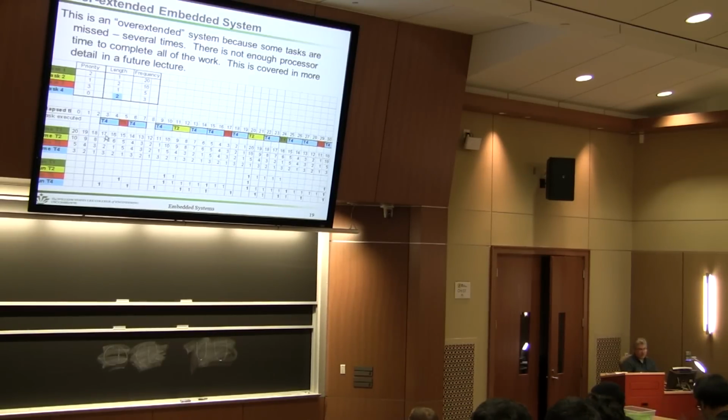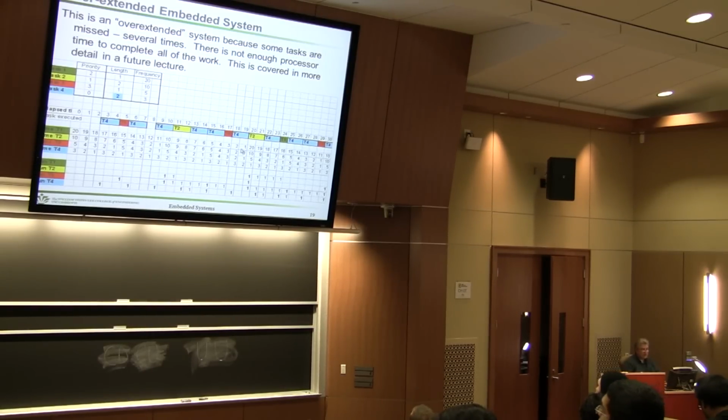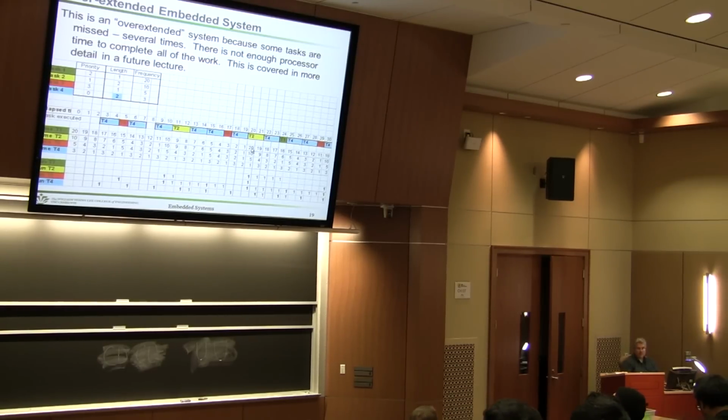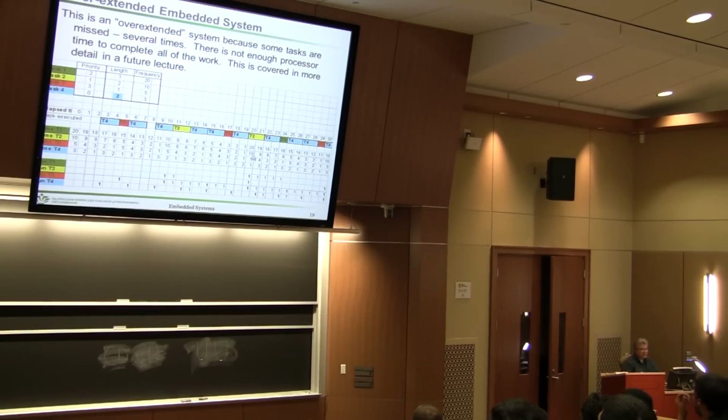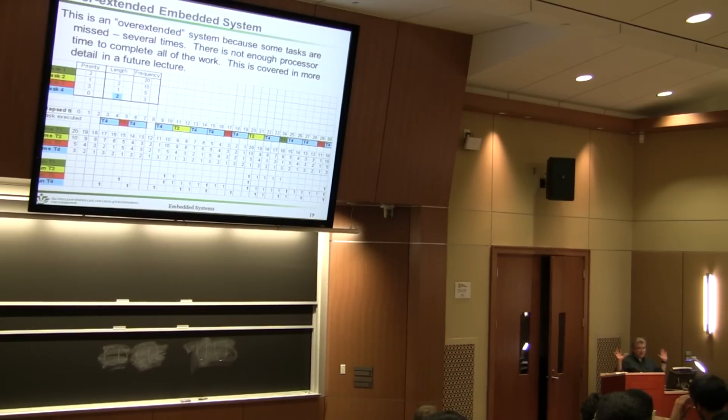Going from 18 to 17. So you'd expect in your interrupt service routine, something would go through each one of the tasks and say, is it ready to run yet? And the way it knows that is by continually decrementing. So at this time right here, when you're going from 19 to 20, the interrupt service routine would run, and it would say, oh, look at this, task 1 just went from 1 to 0. So I'll reset this number at 20, and I'll set the run bit. And oh, look at this, task 2 has gone from 1 to 0. So I'll reset this to the frequency, and I'll set the run bit. Oh, look, task number 3 went from 1 to 0. So I'll reset task 3, and then I'll set the run bit. Task 4 went from 2 to 1, it's not time to run yet. And then the interrupt service routine would exit.